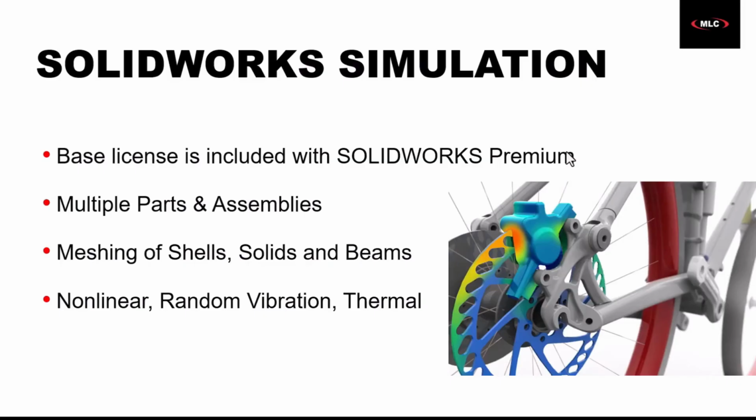We also have way more options for our load types. Instead of just forces and pressures, we can do nonlinear material analysis, we can put in random vibration loads, we can do thermal. There's a ton of options.